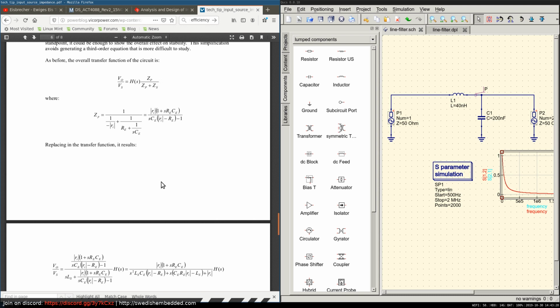So noise can come into the circuit on both the ground and the power line, which would be common mode noise, disturb the circuit and then come out through the chassis. It's not going to come out to the ordinary battery ground, but into the chassis and then the earth ground. That's the way I understand it, but I could be wrong.